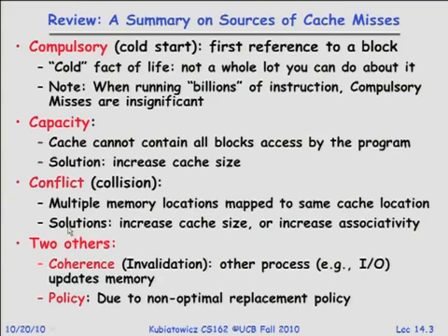And then a couple of other ones. I only mentioned coherence misses last time. The idea behind a coherence miss is you got 2 processors. One of them brought it into its cache, and the other one wrote it. And what you'd hope to have happen is that the hardware automatically invalidates the first cache. First one reads. Second one writes, first one gets invalidated so that when the first one goes back and looks, the data isn't there. And the reason we want that invalidation to happen is because otherwise the first one is going to be reading old stuff out of its cache that's no longer coherent.